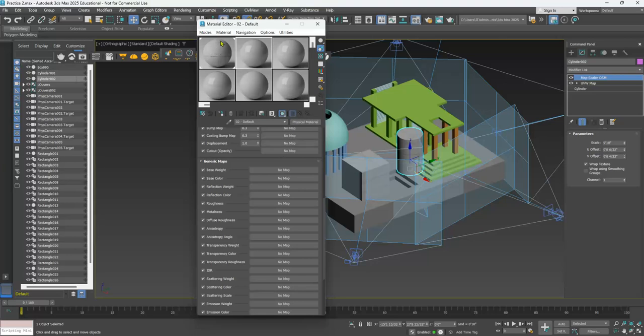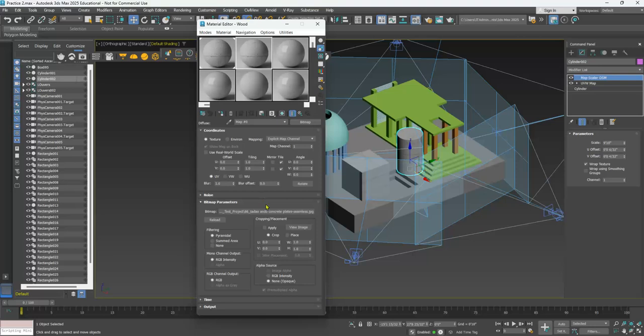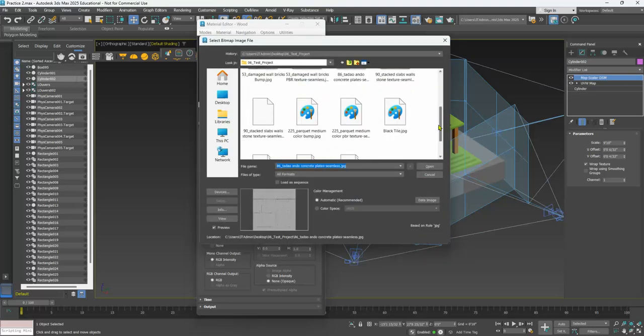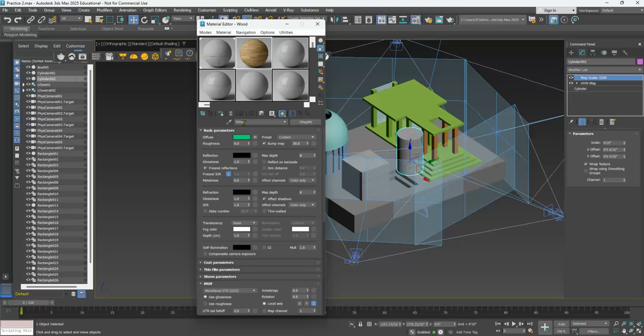Yes. So I'm going to take this one, drag it, and copy here, right? And when I copy, what's the first thing that I must do always? People always forget that: change the name. So let's say we call this wood, right there. I can just go straight to my link here, my folder. Go here to the parameters. It's going to go straight to the folder, and I can just load my texture here. Do it again, and this one here is to go back. So we have wood here. I can copy it again. Let's call it blue tile, no, blue marble.